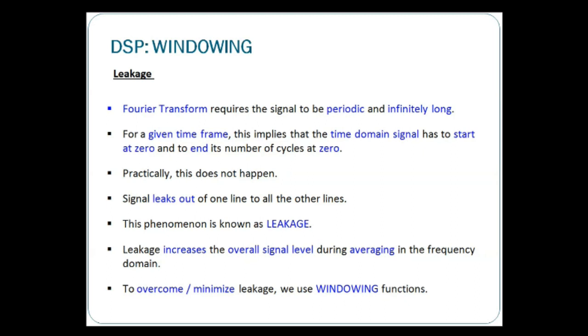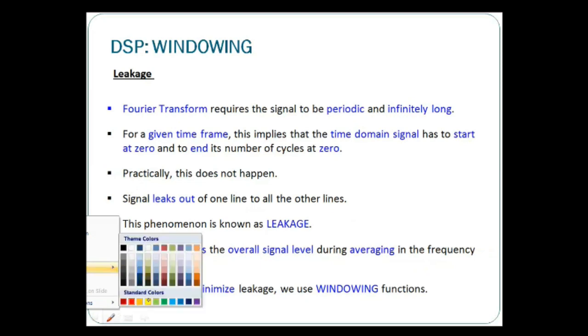Because of the infinite length under the Fourier transform for analog or continuous signals, the effects of the beginning and the end of the signal are very minimal, as it is very long. But under a finite length in discrete signals, the beginning and the end of the signal become an issue. The effect becomes significant when it goes through the fast Fourier transform.